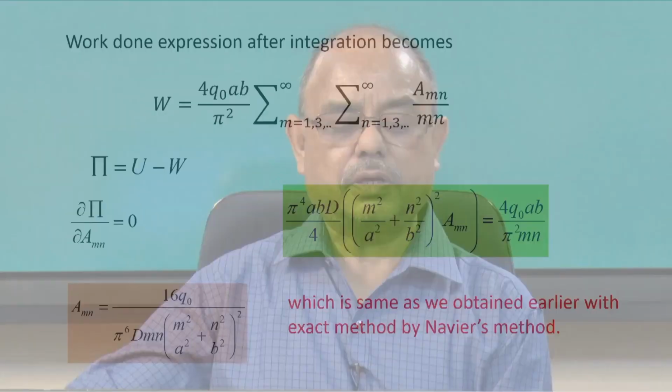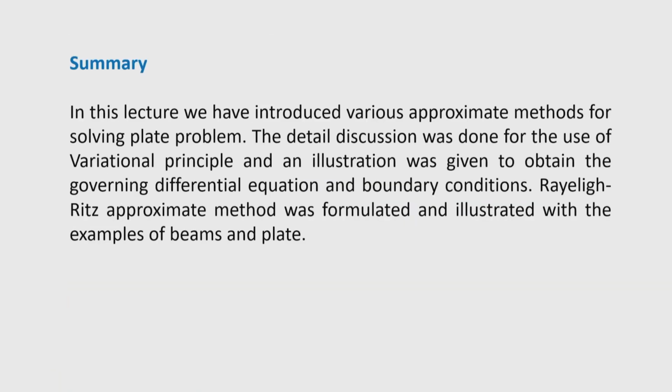Let us summarize today's lecture. In this lecture, we have introduced various approximate methods for solving plate problems. Detailed discussions were done on the use of the variational principle, and an illustration was given to obtain the governing differential equation and boundary conditions. Then Rayleigh's approximation method was formulated and illustrated with the examples of beams and plates.